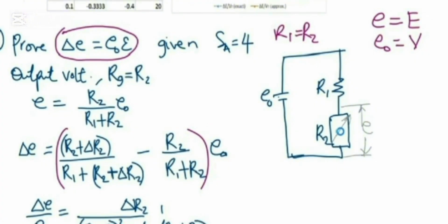But in this case, the loading effect is going to be transmitted in terms of change in resistance, because we can't measure the strain directly. So after it has imitated the loading effect on the actual component or on the specimen, the strain gauge resistance will change. But we cannot determine the strain directly.